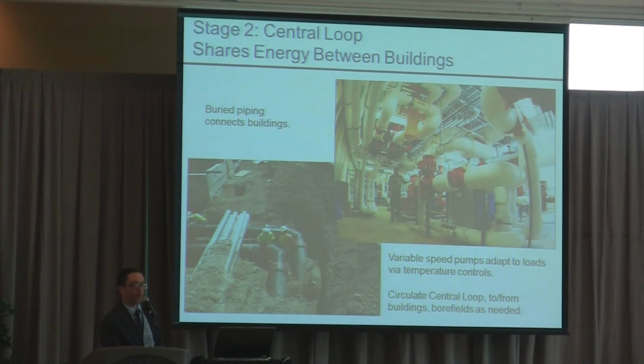Now, when we start looking at a geothermal district energy system and we have that piping in place to connect multiple buildings, before we go to the geothermal system or the conventional energy equipment, we can actually engage those pumps on the central loop and circulate fluid from building to building around a campus through buried pipelines and recover that heat. And what you find is that just like individual zones, I mentioned, that classic example of the south side of the building in air conditioning mode, north side of the building in heating mode, or the core of the building in heating mode.